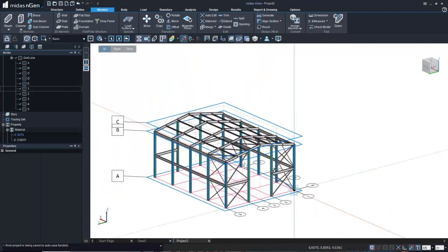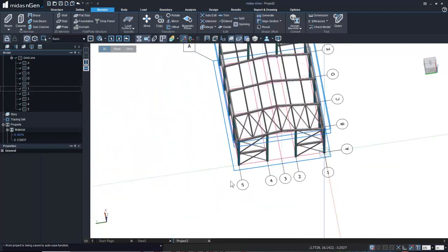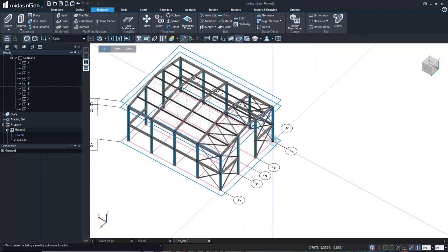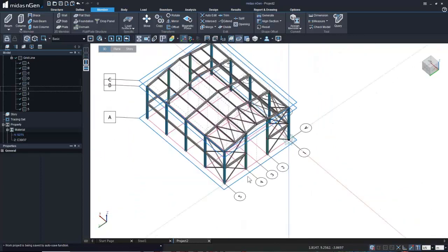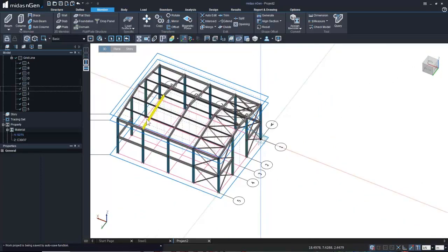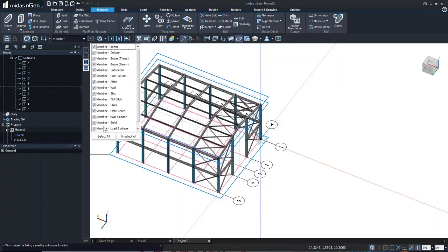Alright, so I have created some braces at one location. I'm going to be similarly creating the braces on the other side. So either I can do the mirror command or I can use the copy command. We have another good option to simply select all the braces together by going to member type of selection, and then over here we have different members.